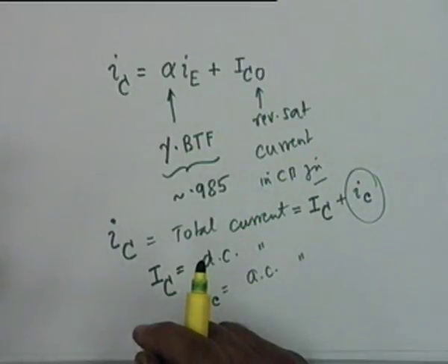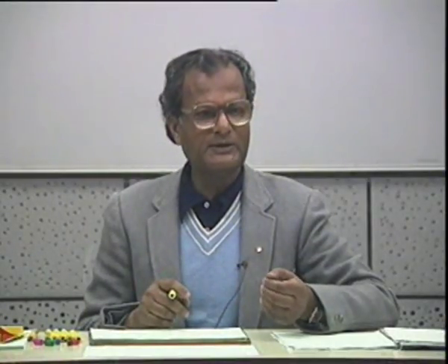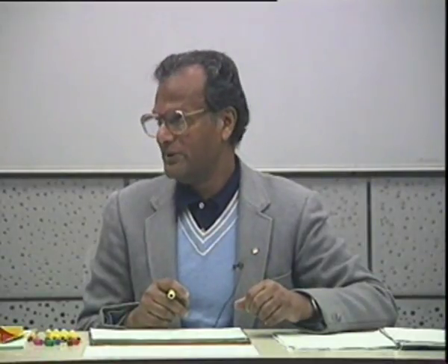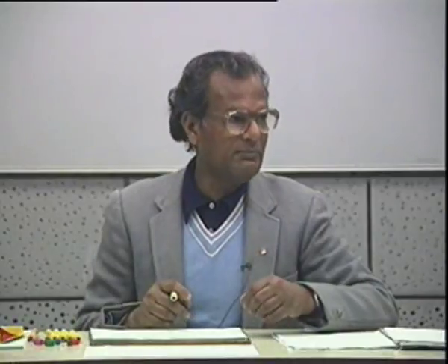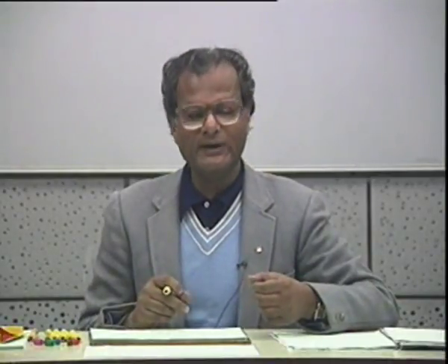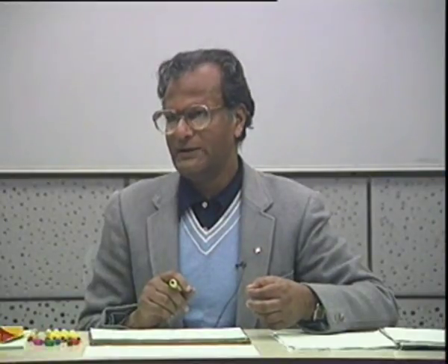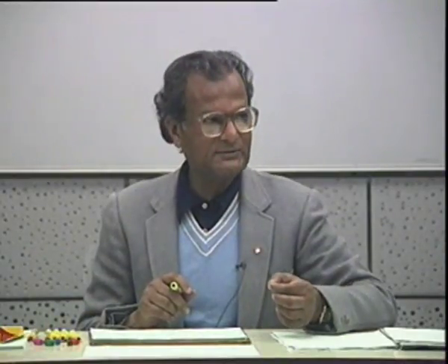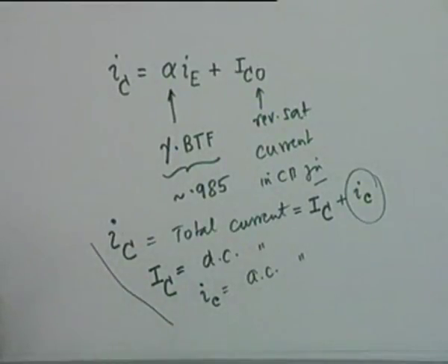It is necessary for a transistor to be biased at the appropriate Q point or the operating point to be able to function as a good amplifier or for other applications. It must be biased appropriately, and it is the incremental part of the voltages and currents which shall be of interest. Nevertheless, we shall use this terminology for the rest of the course.